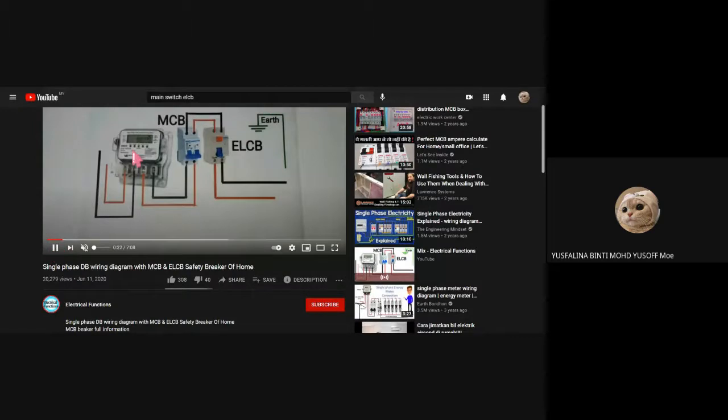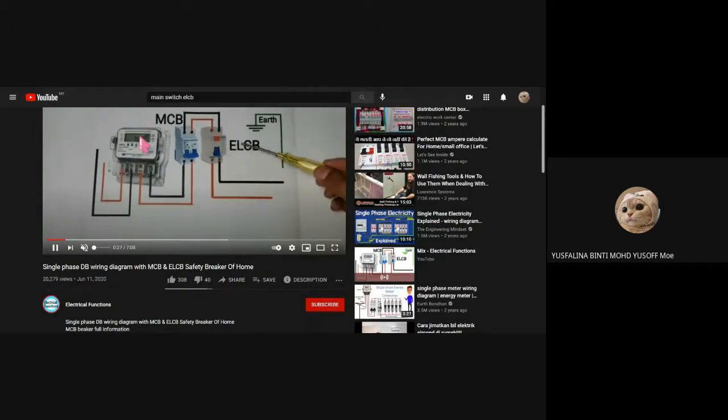Okay, so I just shut down the sound. So this is actually the electric meter, and then it will connect to the MCB here, and then it will connect to the electrical circuit breaker. Then they will divide the current to the appliances. So this is how the wiring in the house works. So this is the electric meter, this is the MCB, this is the ELCB.